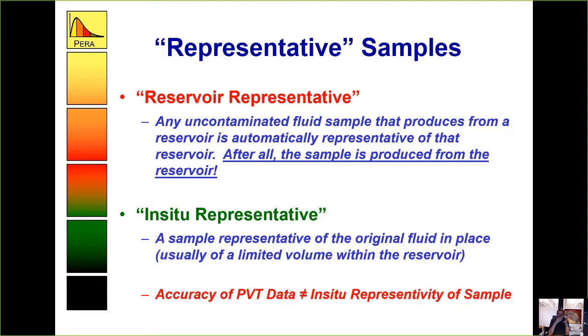And certainly, for maximizing the liquid recovery at the surface, you need some kind of model to tune the surface processing. So you need an equation of state for many reasons. So you'd like to develop an equation of state based on quality data. And that's the one reason that you collect samples and measure PVT data.